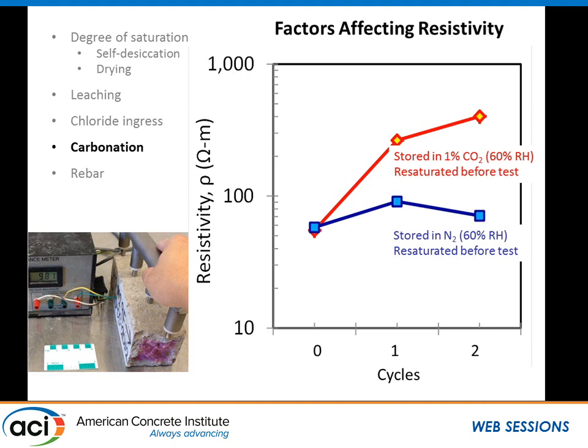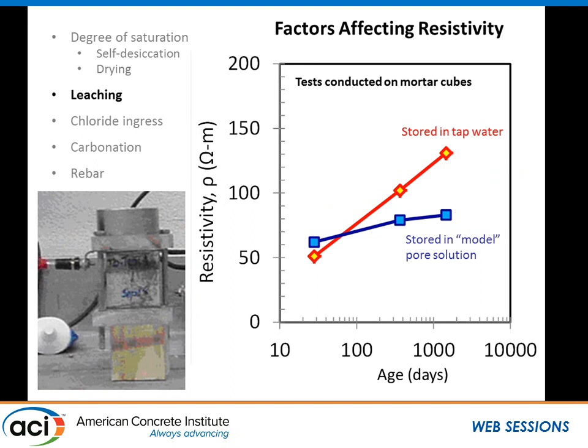In fact, if anything, you've very often increased the chloride penetrability because you've lost binding capacity of some of those hydrates. Now, it's true that carbonated concrete tends to have a denser pore structure, so those two things might compete. But there's one thing that can have a big effect.